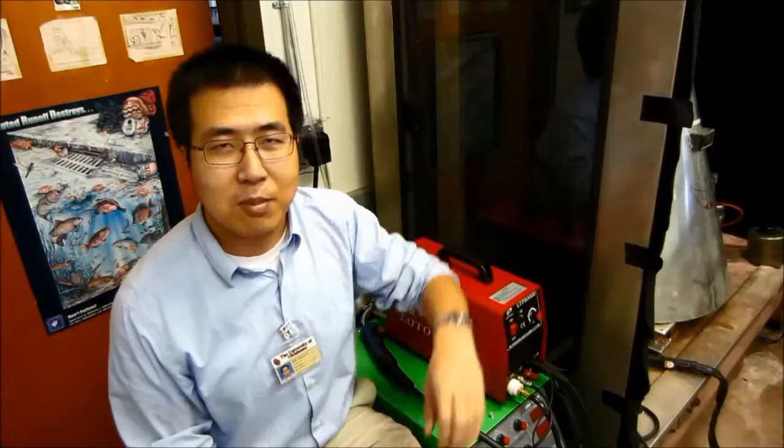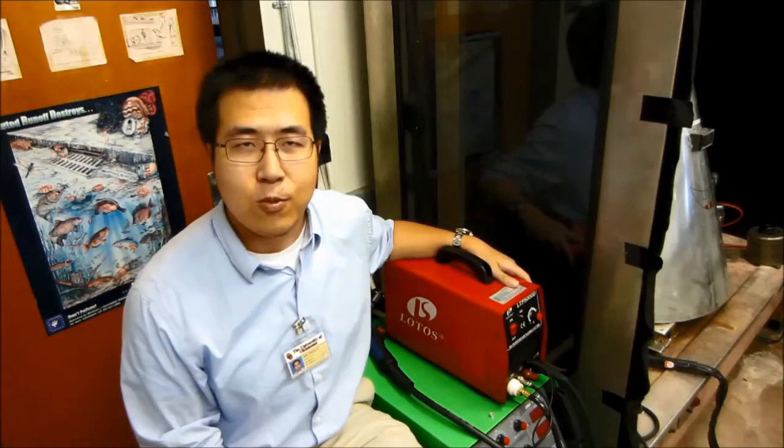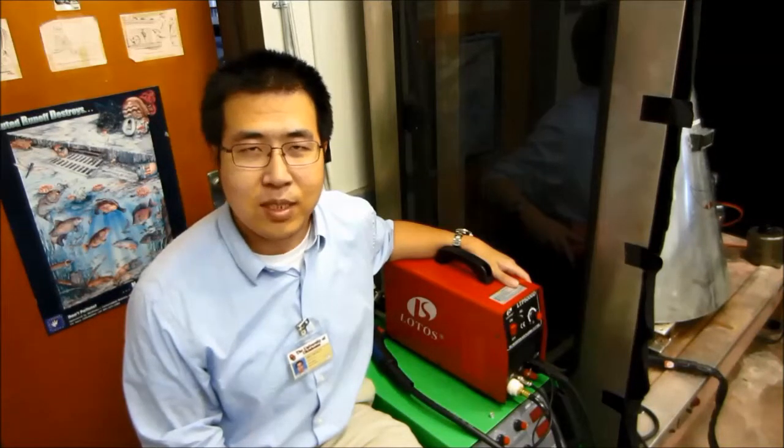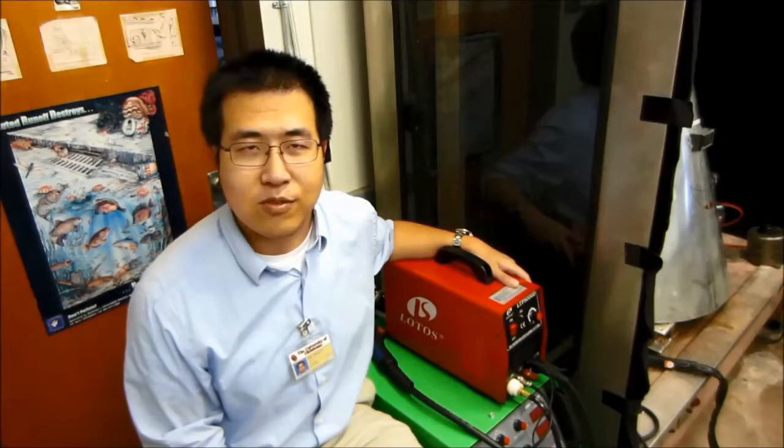The study showed plasma cutting performed on stainless steel will emit a high concentration of aerosols in the ultrafine and micron range, loaded with hexavalent chromium in the fume. The higher the arc current, the more total fume and particles generated.